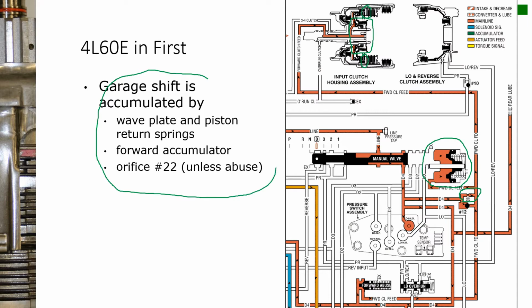If you have an issue where it slams in the gear or it slips in the gear, you probably have an issue. If it's slipping, you might have an issue with leaking or low pressure. But if it's slamming in the gear, it's possible one of these items are not doing their job here.